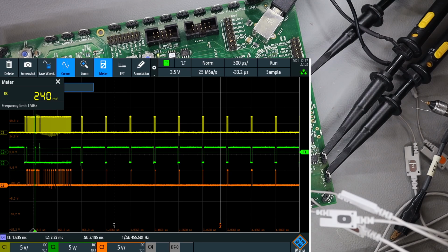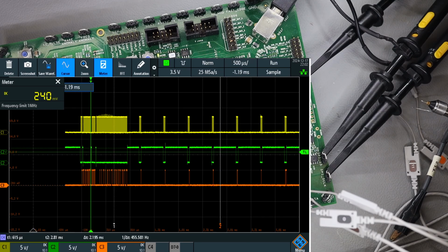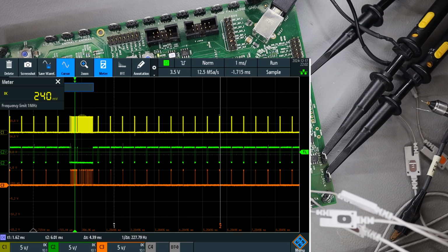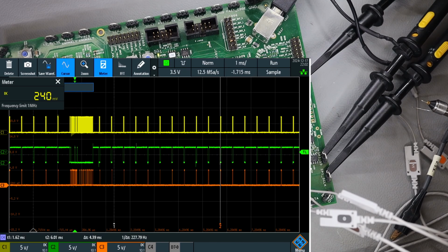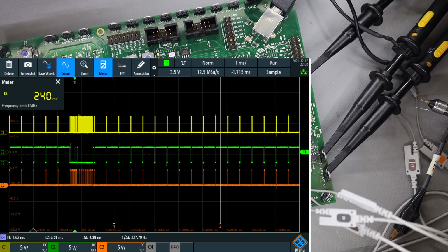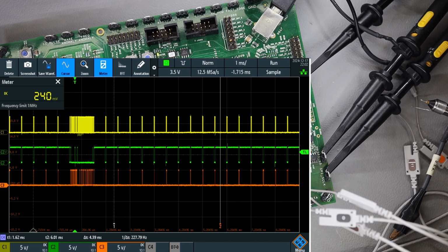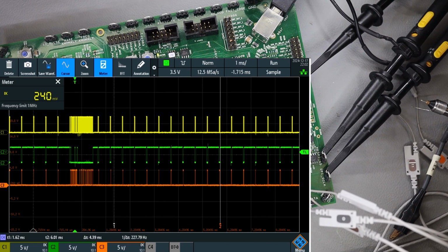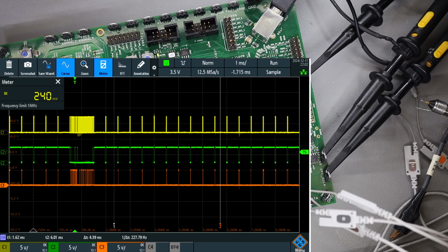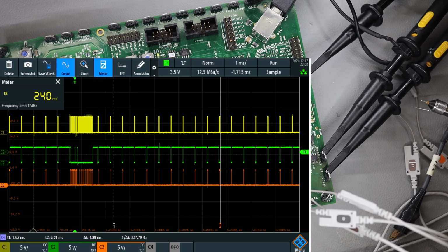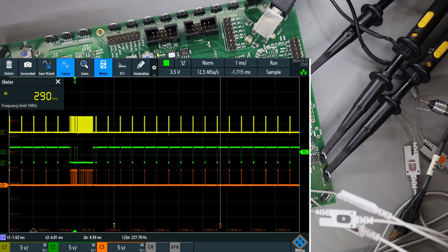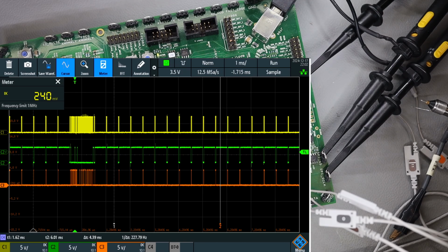You see there is a big massive packet. For some reason I do not understand what this packet says. We will soon decode it and find out. So you see sometimes these small packets come, sometimes this big packet comes, and we have a non-repeating or rarely repeating packet available on the scope. Using a slightly advanced trigger, the pulse trigger, we have found the packet. So this is just a tip: with a pulse trigger you can easily find the packet which you are interested in.